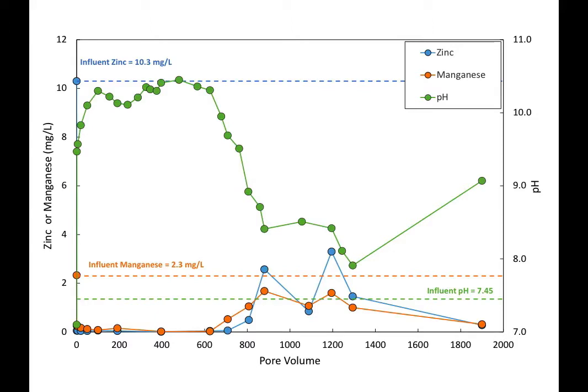And I think we got a little bit of help because the system started to plug a little bit, and it was slowing itself down. The hydraulic retention time within the system was only 15 minutes, which is very quick. In a traditional limestone system, you'd be looking for 24 hours while the water's sitting in the reactor and kind of making its way through. So this was pretty promising. It did have some issues. And that's why we've thought about some other ideas. But I still think that this could be applied in some interesting directions.